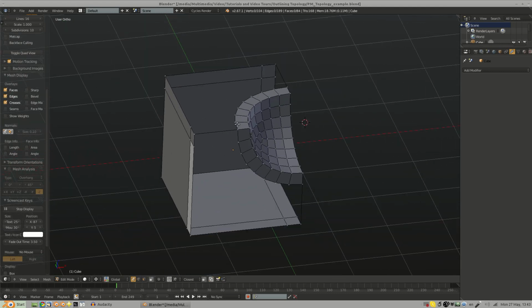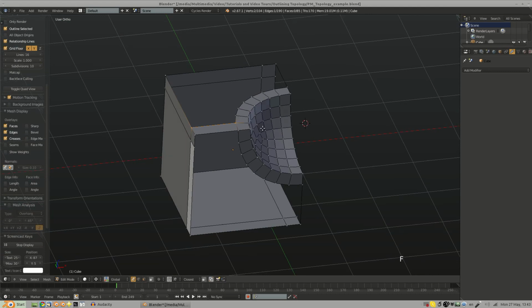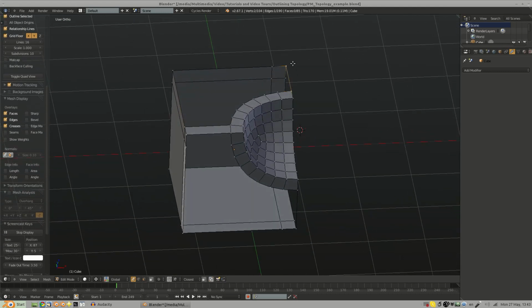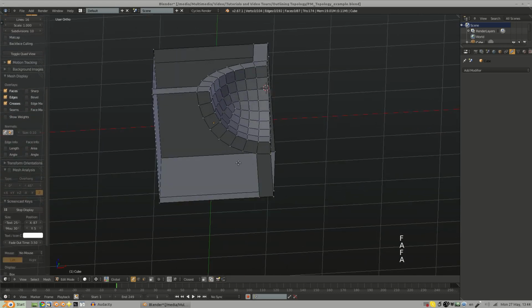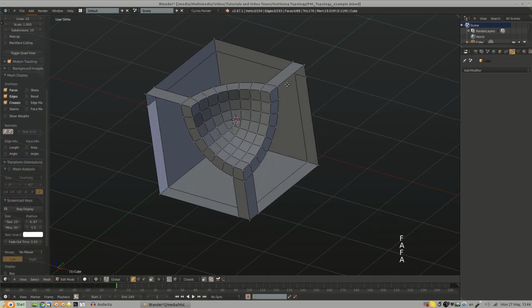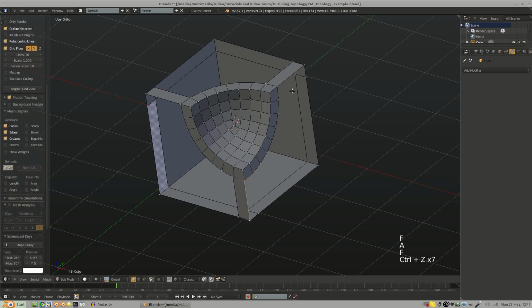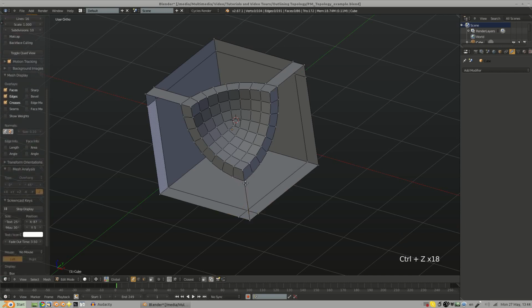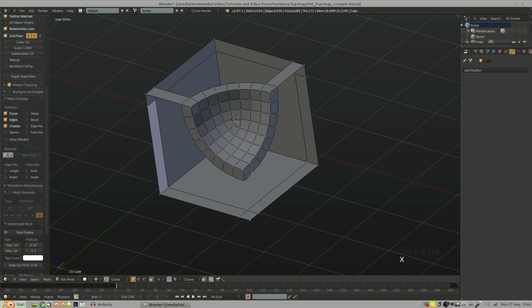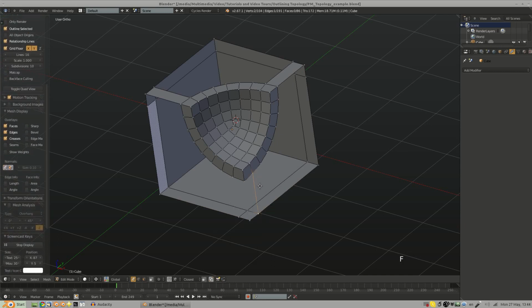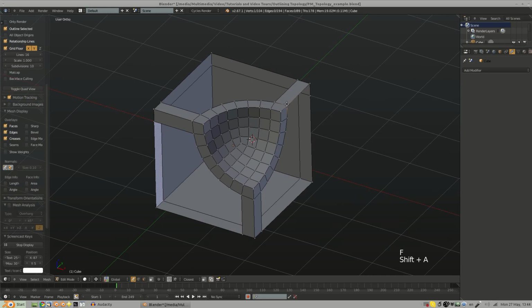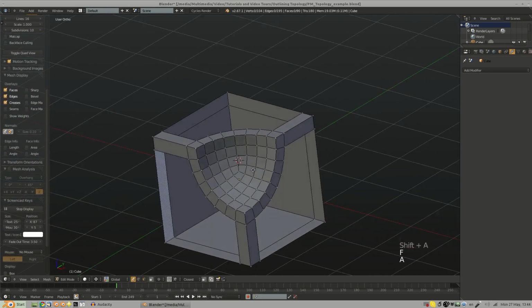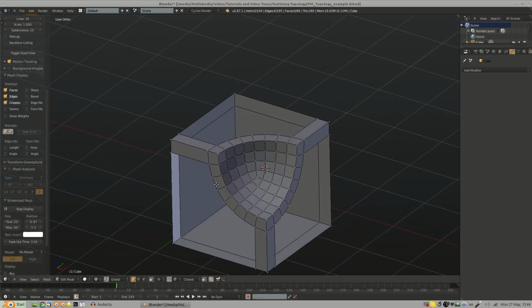So just to make sure that our edges here line up properly, as you can see, I'm filling in faces just by selecting one edge. That's the F2 add-on in action. Actually, let me just show this properly. I'll delete this edge just to show it off properly. Select these 2 vertices, fill them in to create an edge, and then click, click. Fill that in nice and quick. So I'll just fill these in. So that would be the basics of what we're going for.